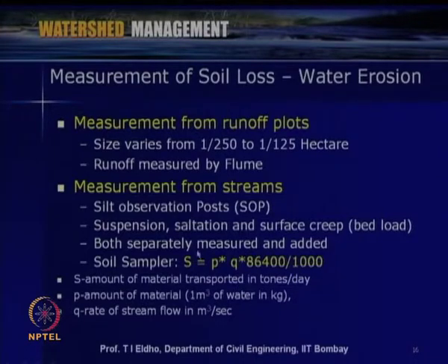So, like this, we can do sampling in channels or rivers, and from that we can measure how much the soil erosion will be, especially due to water erosion. Now, we have seen as far as water erosion is concerned, various factors, various causes, and various types of water erosion also.